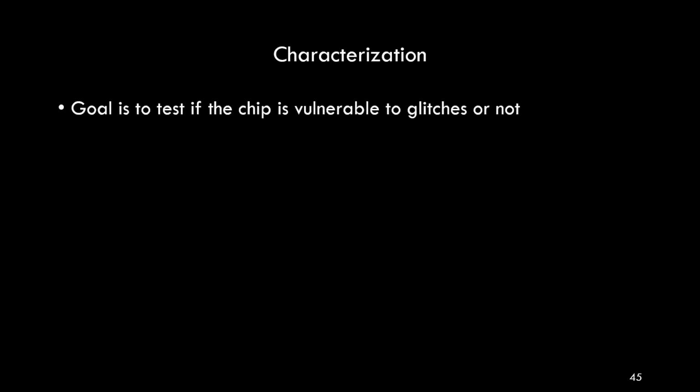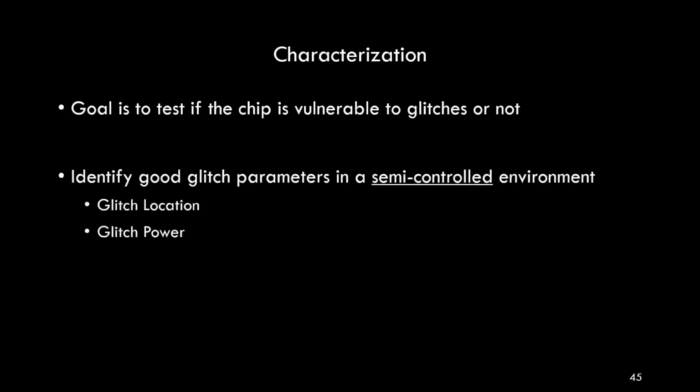So one of the first steps that we like to do is to perform a characterization step in order to test if the chip is actually vulnerable to glitches or not.